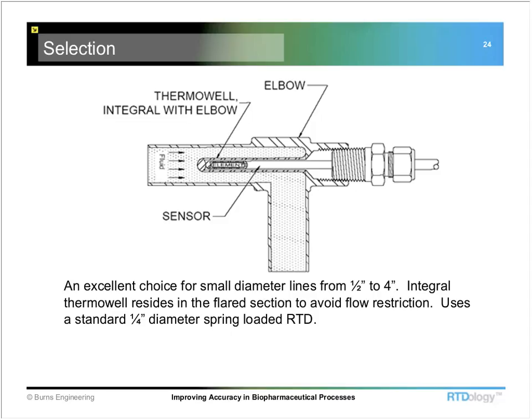It does make a big difference in time response, and it does eliminate any air gap between that probe and the thermal well. So you do get a lot better heat transfer characteristics.